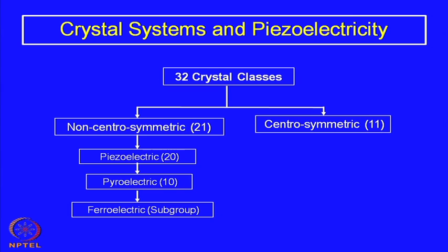Okay. So, one important aspect you have to remember: all ferroelectric materials are pyroelectric and also piezoelectric. Any ferroelectric material is supposed to have the pyroelectric property as well as piezoelectric property. However, all piezoelectric materials need not be ferroelectric, some of them are and some are not. For example, quartz is a very important piezoelectric material extensively used in industry, particularly the electronics industry, but it is not a ferroelectric.